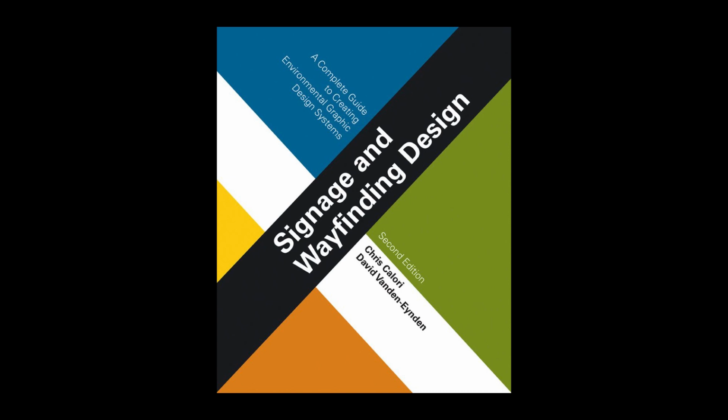The review stamp may belong to the EGD office or to another firm on the project team, such as the architect, or the review stamps of both may be used. In addition to the status checkboxes, the review stamp typically contains a disclaimer of the reviewer's responsibility, along with spaces for the reviewer's signature and review date. The review stamp status is accompanied by any applicable review comments written on the submittal.